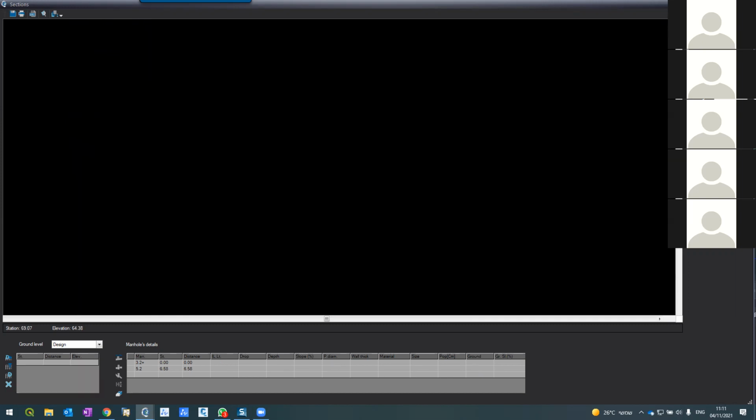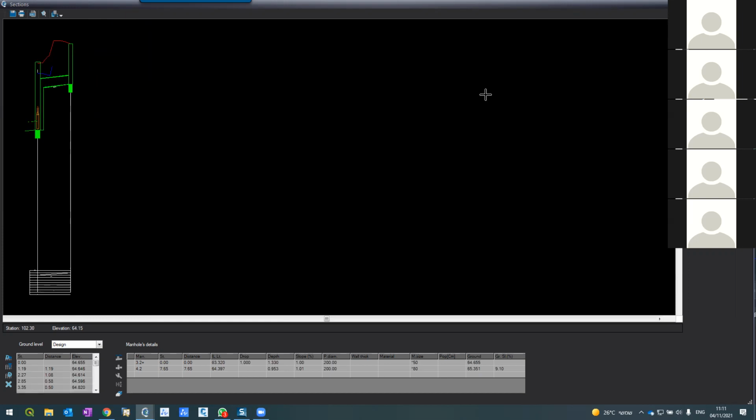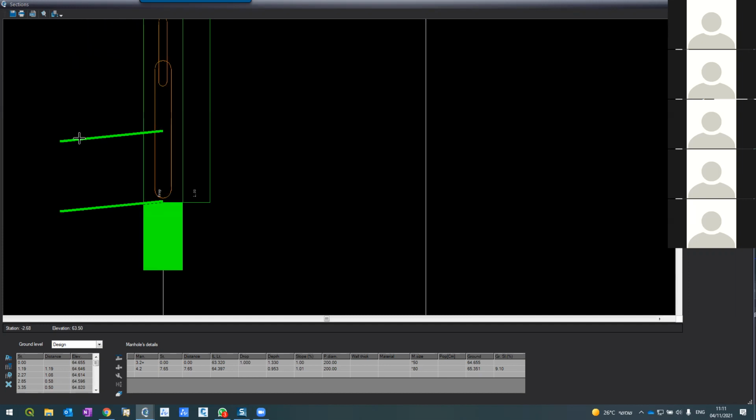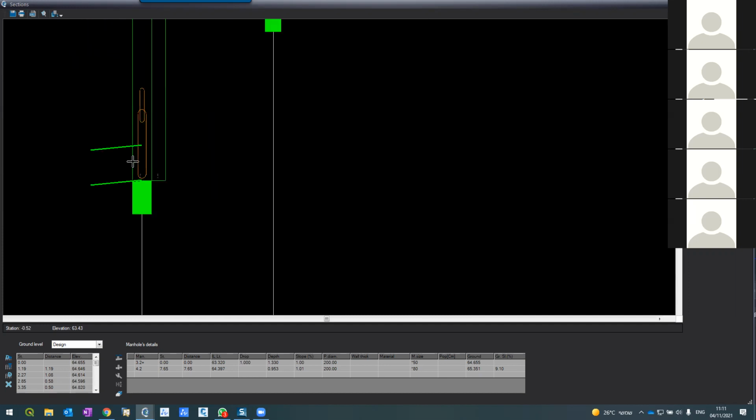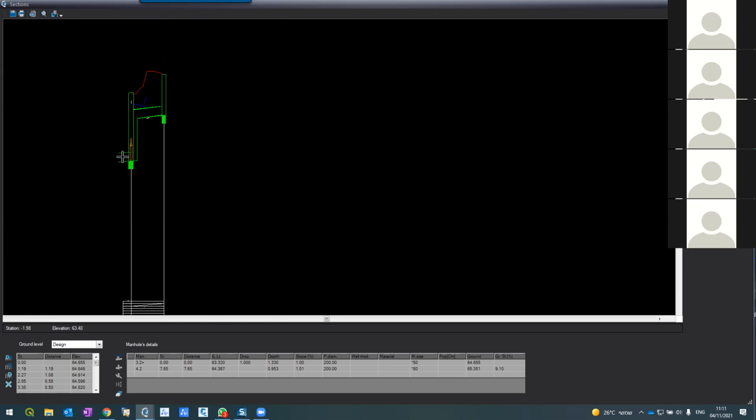P6. So this is the way how you do it. And the software gives you even a simulation where there is a pipe going from here out. So again, I'm starting with the same invert level, and if I want to connect at a higher point, I just do a drop here. I hope it answers your question.